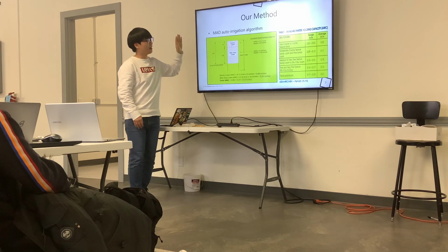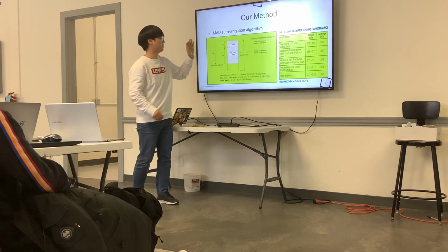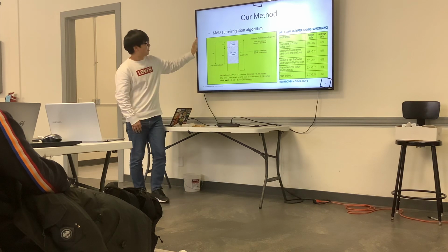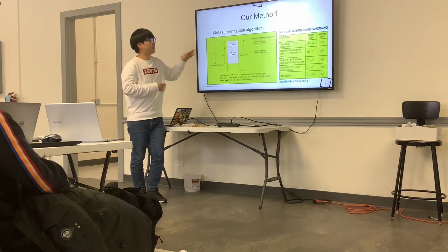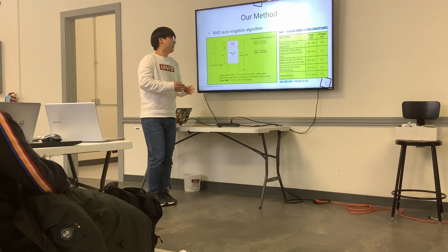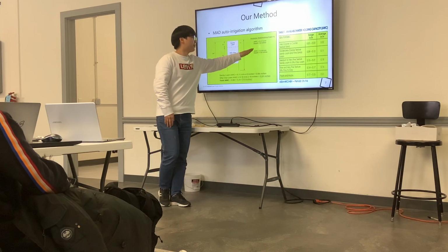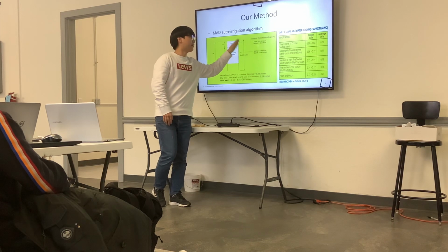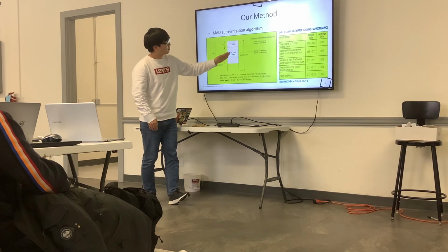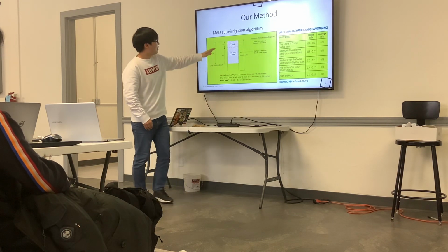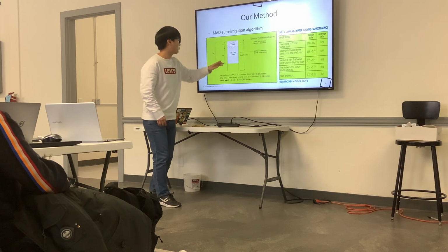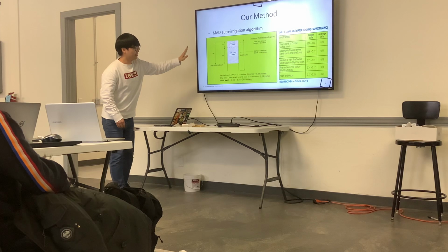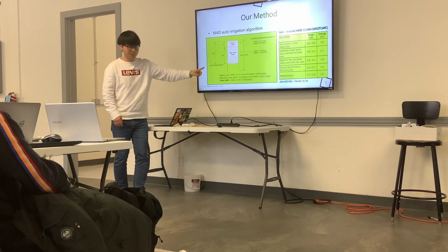Sorry. For sandy loam, the average AWC is 0.11 water inches per soil inch. This part's depth is 6 inches. So sandy loam AWC is 0.66 inches.